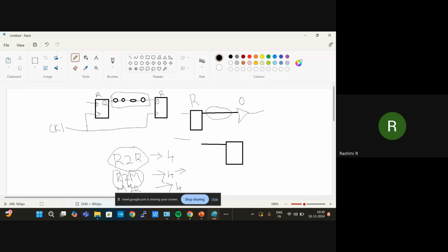Mem to reg also the same way, and inputs to register. Mostly we will give high weightage to reg to reg, reg to mem, and mem to reg path groups. The tool will keep all these path groups in mind and do optimization.